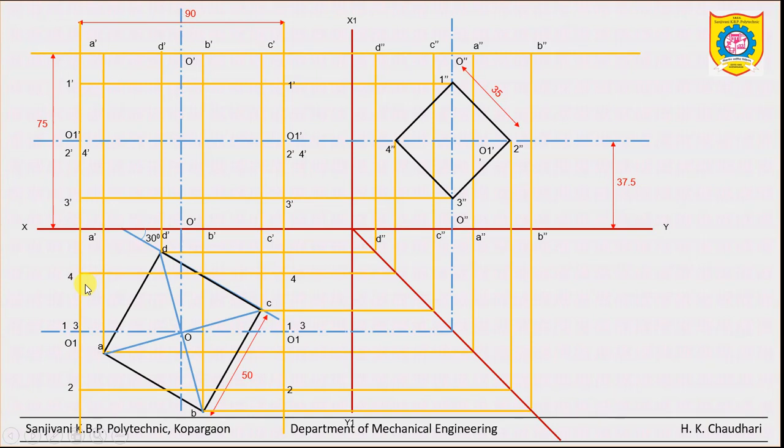Clear? And now see, locate the point. Now see edge number 1. It starts penetrating the vertical prism at this point, okay, here at Q1, and leaves the prism at P1 point. This is P1 point.